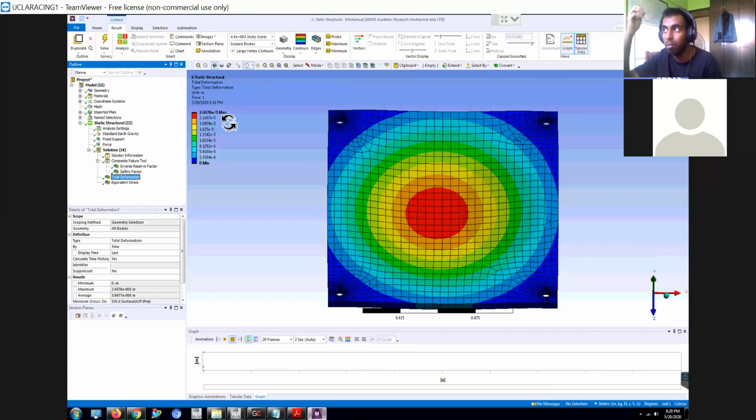And also, the more plies you have, the more risk of defect you are at. So generally try and keep everything below 12 plies. I find that's the sweet spot. And yeah, as much as possible, try and reduce the thing. All right, so that's pretty much it for ACP.